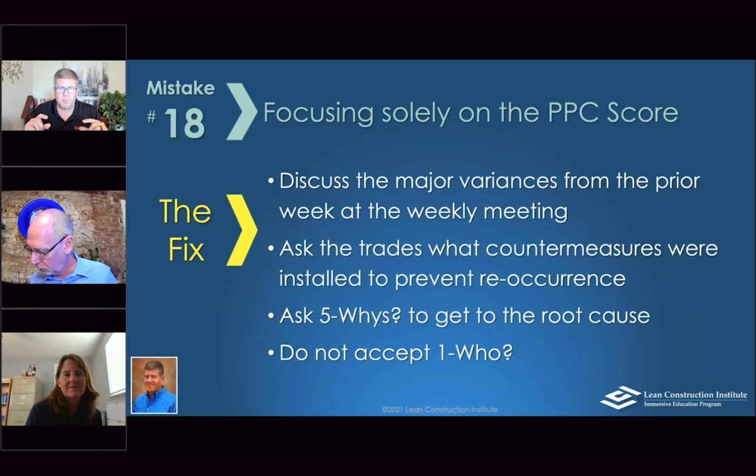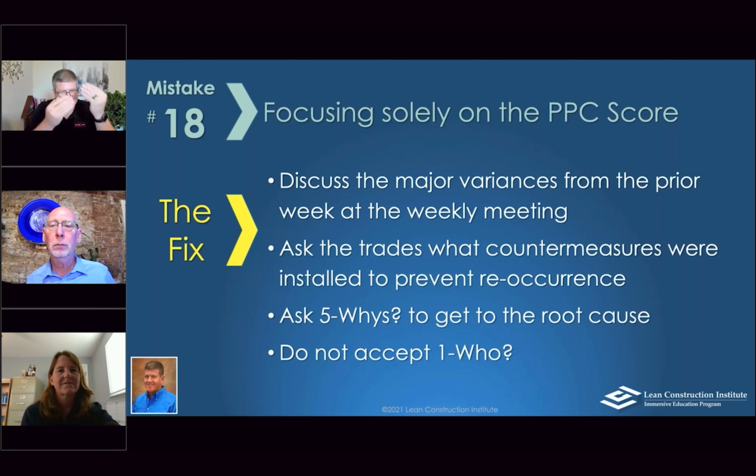So one of the things in the pull plan prep is to get everybody speaking the same language. And I don't care whether it's French or Russian or Chinese or Japanese or English, but we're all going to speak the same language, right? So we're all going to call it the same thing. We're all going to call it area A, right? On our sticky notes and everything, so we can see the area A or the level 1 or zone 2. Doesn't matter, but everybody's got to speak the same language. So often we don't do the prep, and people fill out sticky notes with whatever they think the areas are, and they're completely useless because it's like the Tower of Babel.